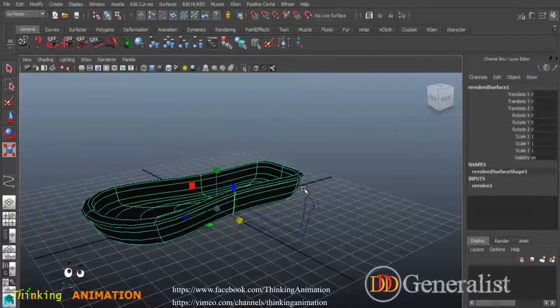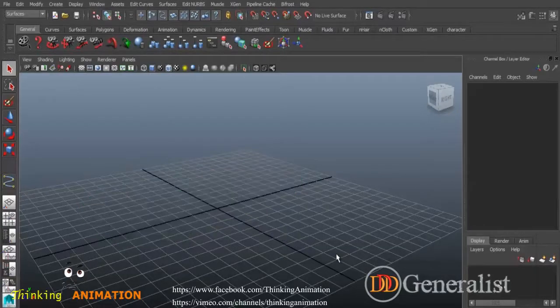So modeling is all about exploring and understanding and observing your geometry and your objects, and this way you can easily model different kinds of stuff. So all the round shapes, those have the 360 degree or even less than that angle, you can just create them with a revolve. So select both of them and delete.